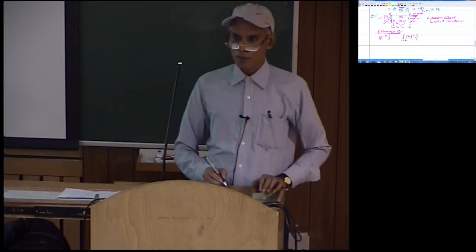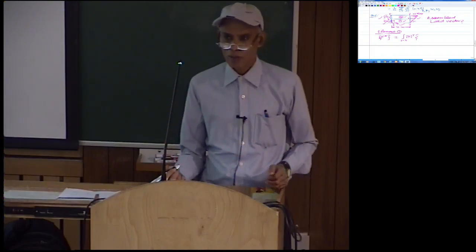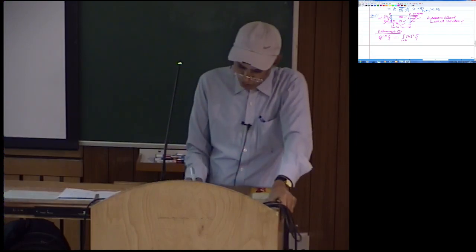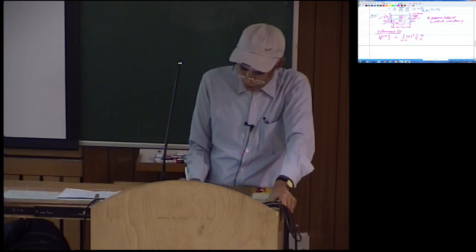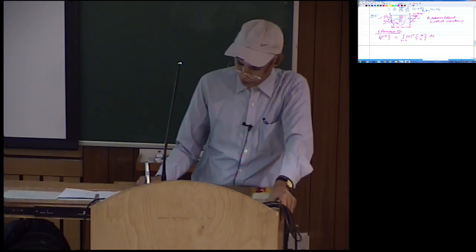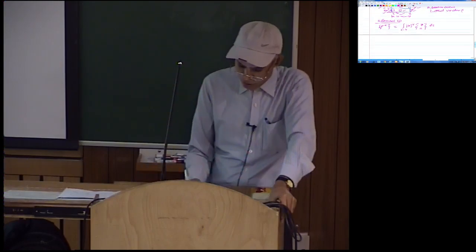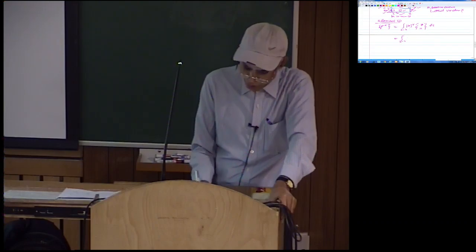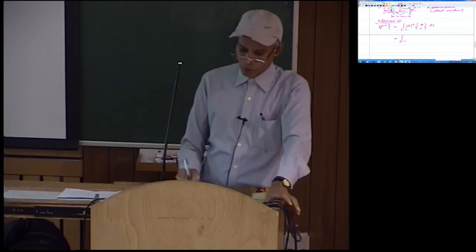So the load intensity is varying as 1 Newton per meter square. So you can say the load along the x direction is essentially y, and along the y direction the load is 0, and then integration ds. And here, since the second is 0, finally you would see this integration 2 to 4 H transpose, again for a 4 noded element.